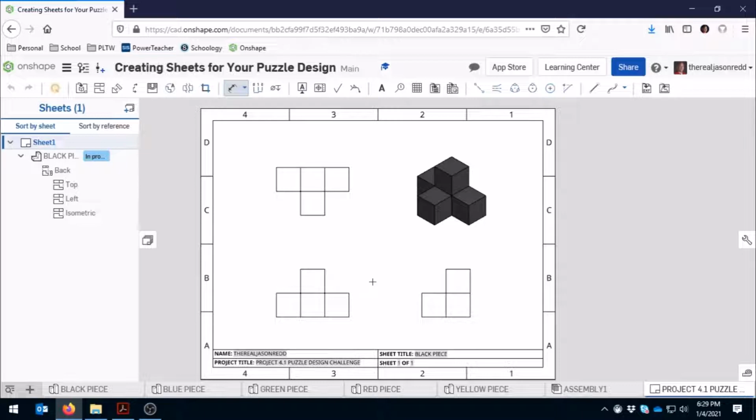We also need to show the depth dimensions. Those are shown in the top view and in the right side view. Again, you can show those in either one, and I always just try to choose which one works best at that moment. Sometimes I have to add a height dimension in the right side view, and because I add one little view in that one, I choose to add the depth dimensions to the right side view.